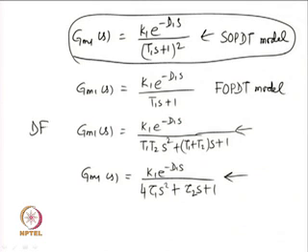We shall make use of describing function in our analysis. When you make use of describing function in your analysis, the describing function does not result in more analytical expressions, only the phase and magnitudes of describing functions or the analytical expressions involving describing function can be considered. In that case, the number of unknowns that can be identified will be limited.